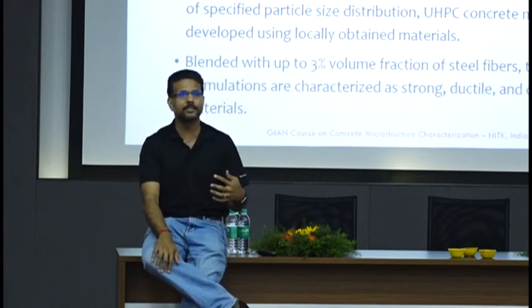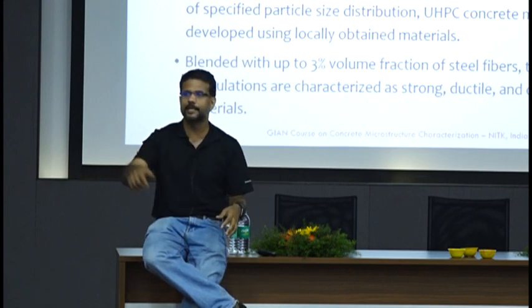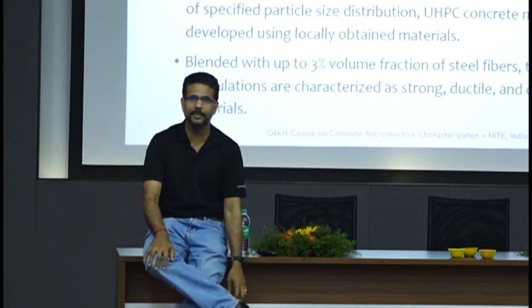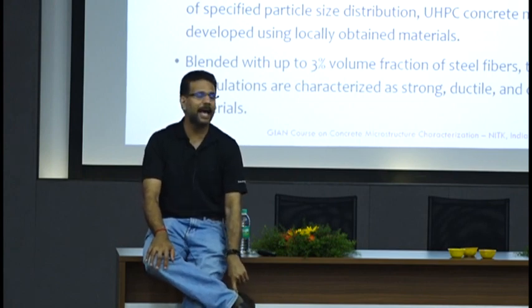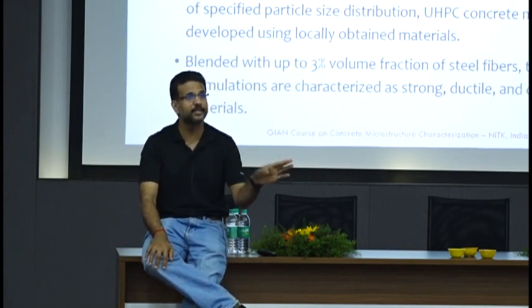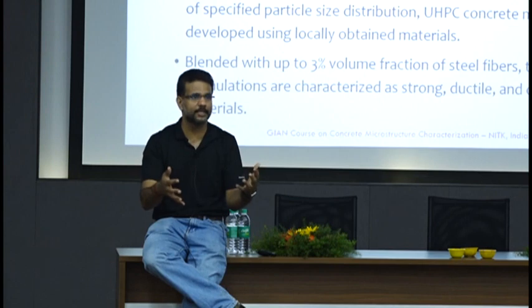So anybody who has told you that fly ash contributes 20% of strength, cement contributes 90%, silica fume contributes 10%, is just plain lying to you. He probably got it in one result. There's absolutely no way that is true for another set of mixes. Okay? So you can define the reactivity of a material. So that's what I would suggest.